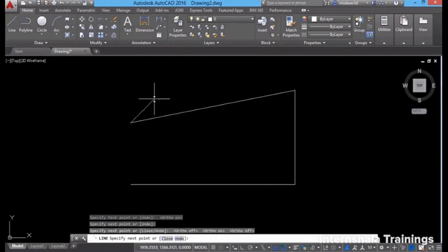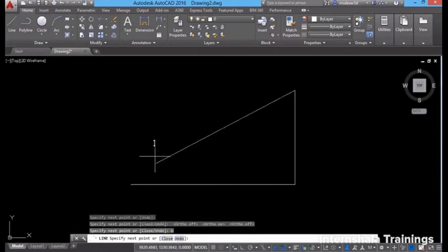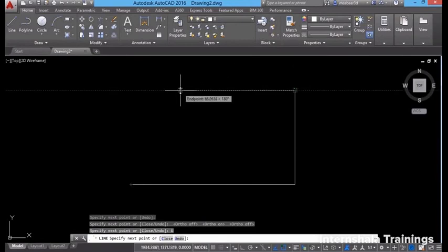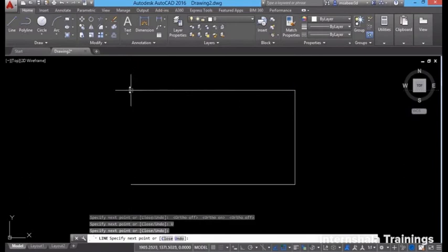Now I've got that point exactly on that vertical tracking line. I'll undo this. Now I'll track this endpoint once more, and I'll track this particular endpoint as well. Now when I move the mouse leftward, I will get the point of intersection. Now just make a click there. I've got that point of intersection. Now you can close it.